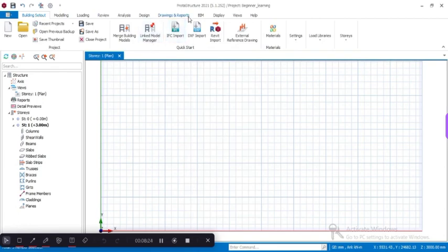So that's an aspect of Prota that actually gives more efficient time usage, because it's a shortcut to just import everything from your architectural drawing. So let's go through the quick start guide. The active layer, we already explained everything there. Now let's move to import the DXF.